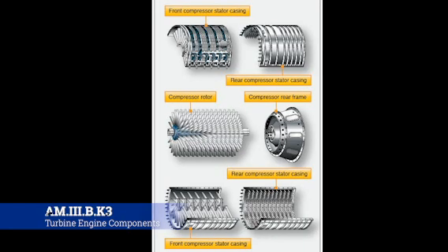Now, in my experience, this is going to be the more common one. It's an axial flow compressor. So it's got two main elements: a rotor and a stator. Rotors turn, stators stay. The rotor has blades fixed on a spindle. These blades impel air rearward in the same manner as a propeller does, because of their angle and their airfoil contour, which is really important when we get to blending blades: remember that the way you blend a propeller blade and the way you blend a rotor blade is basically the same.